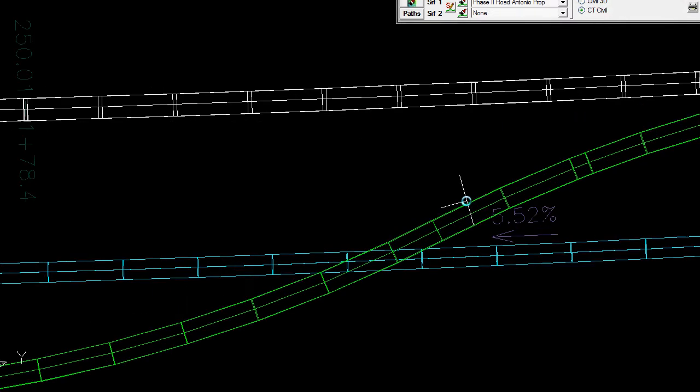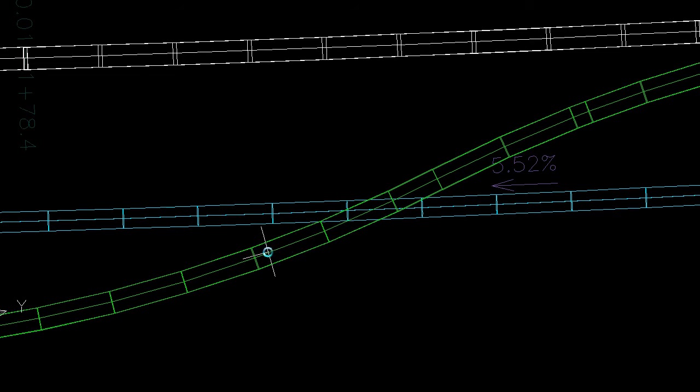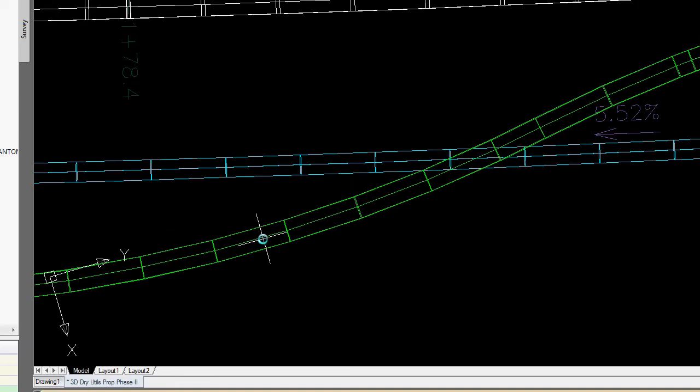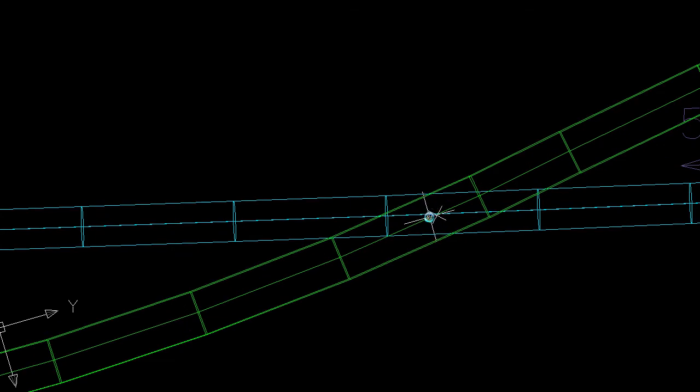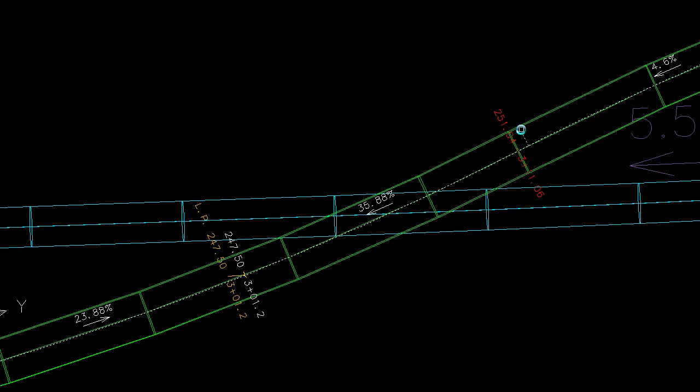So I'm just gonna pick and snap to the backbone, so that puts a break in there, even though currently the slopes on both sides are the same. I'm gonna need that because when it comes down, I'm going to need it to start its dive right there. So then I'm going to add a point here, snap to the waterline invert, edit that, 248 to 47.5, move it over to here. I'm going to edit this one to match to 47.5 and return to finish. And let's take a look at what that looks like in 3D again.